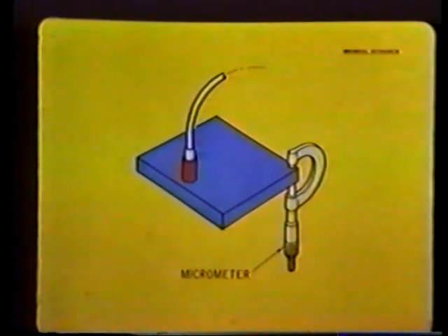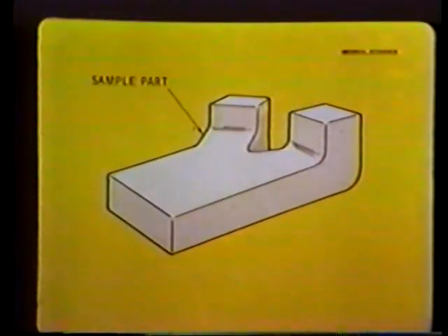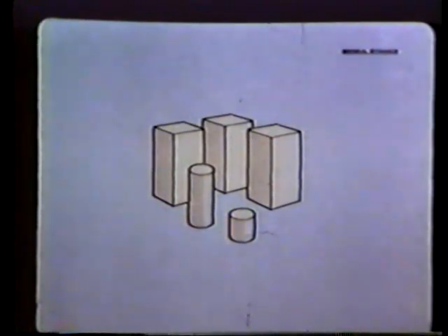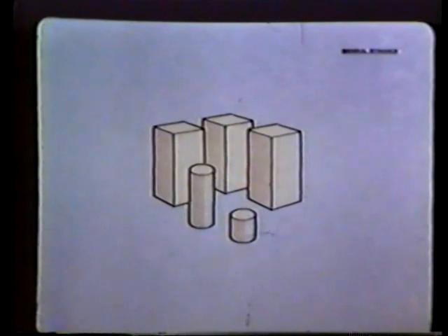No matter what is used as the reference standard in calibrating or standardizing, be it a sample part or some form of test block, the material properties must be like the material being tested. The same grain structure, hot-cold working, heat treat, the same surface condition. Only then can we assume test results will be valid.